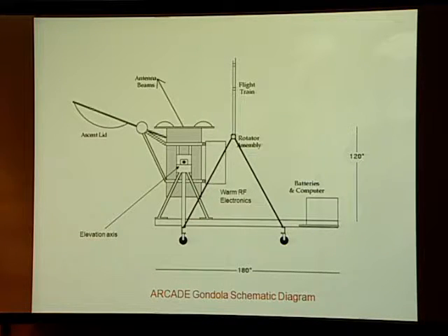So how do you get an instrument cooled to approximately the same temperature as the background you're looking at, in this case 2.7 Kelvin? How do you get that to survive with no window? Well, the idea here was to have helium gas that boils out of the dewar, forms a cold puddle of gas, and that serves as a thermal barrier between the instrument and the residual atmosphere outside.